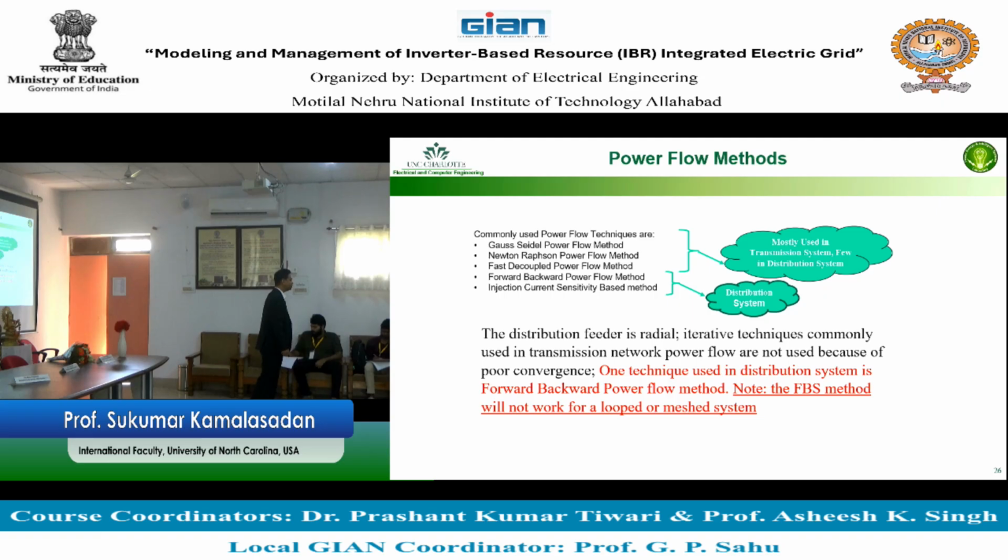What do you mean by positive sequence? Well, positive sequence is the same as all the phases' power added together, or one phase power multiplied by 3. This is basically the same as positive sequence. So if you convert from phase domain to sequence domain, and if the unbalance does not exist, the positive sequence representation will be the same number as your phase representation. So you run in the positive sequence representation, and you don't have to do divide by 3, multiply by 3, and then per unitizing, and then messing up the numbers is not an issue. All those things are avoided if you run in a positive sequence representation.